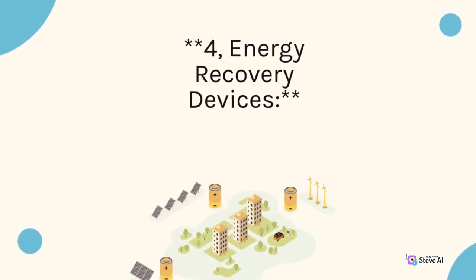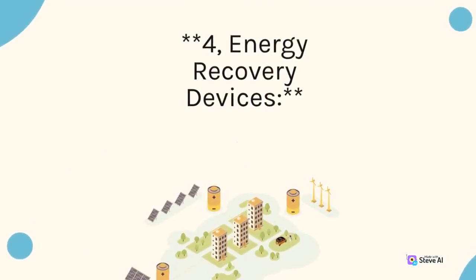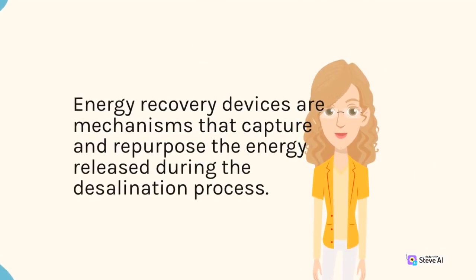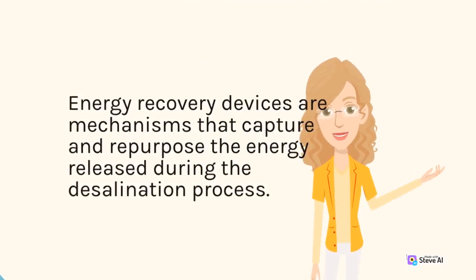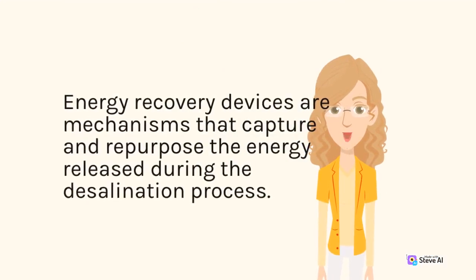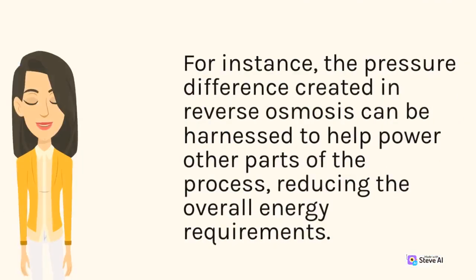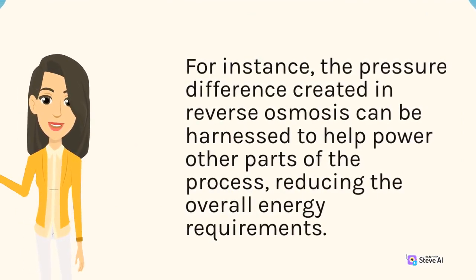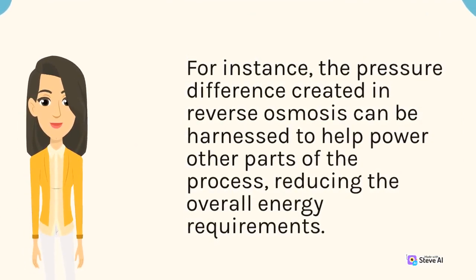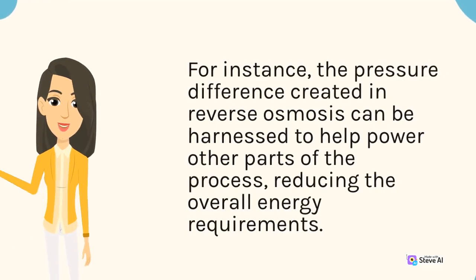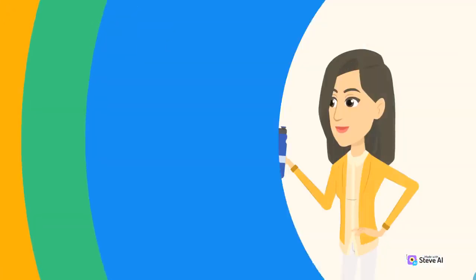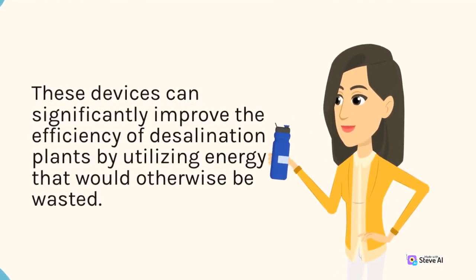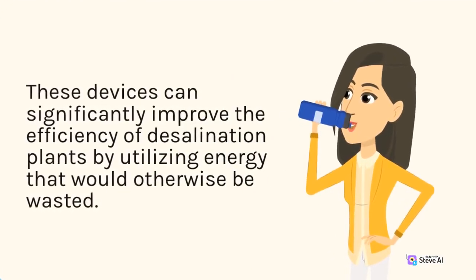4. Energy recovery devices. Energy recovery devices are mechanisms that capture and repurpose the energy released during the desalination process. For instance, the pressure difference created in reverse osmosis can be harnessed to help power other parts of the process, reducing the overall energy requirements. These devices can significantly improve the efficiency of desalination plants by utilizing energy that would otherwise be wasted.